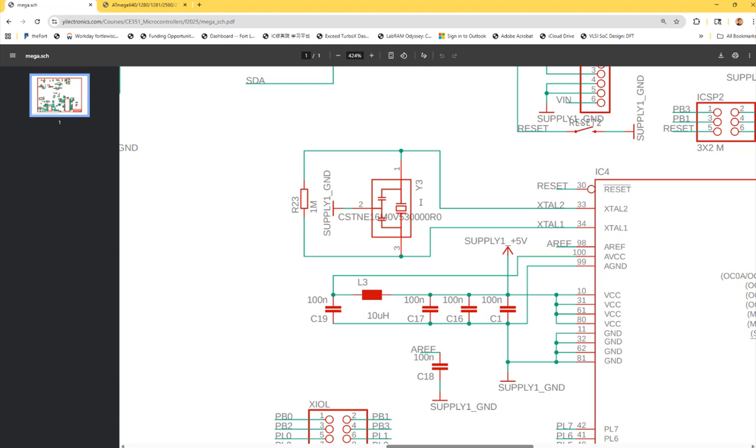So you want to follow a better practice. It's a better oscillator to use, and we did use it for the skyboard. So just to place it, this is available in the library. Just place it in your schematic and make the connections. Very simple. Boom, boom, boom. 3 connections. So ground in the middle and have 2 connectors to the 2 inputs. It's a differential input for the oscillator, for the clock in, right? Clock.